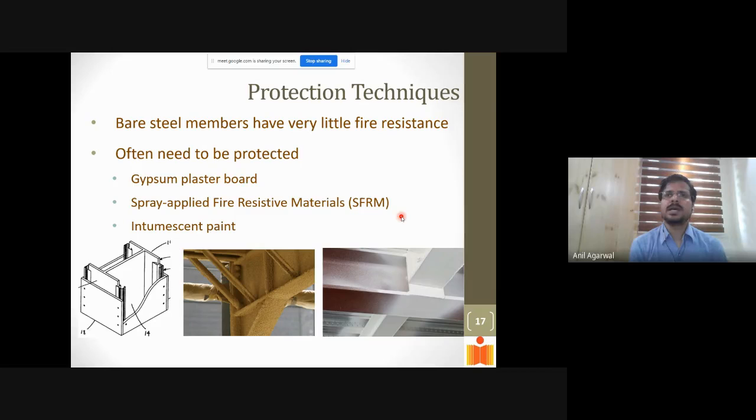But actually, live loads are not present 100%, so you can reduce the live loads. We are often allowed to take 50% of the live load, not the full 100%. If you do that, you reach around 55%, 60%, right? And if you take away all the other factors of safety, material factor of safety, everything else, then you are at around 45 to 50%. Because there will be other design conservatism built into the design provisions. So you are at about 45% or 50% of the actual capacity of the column when the fire hits the structure.